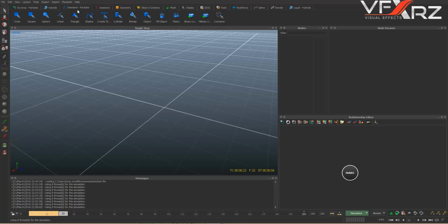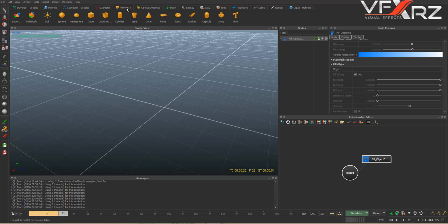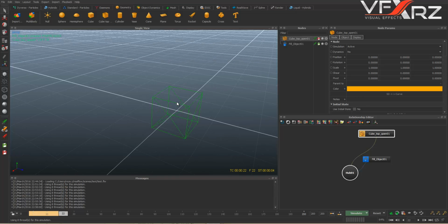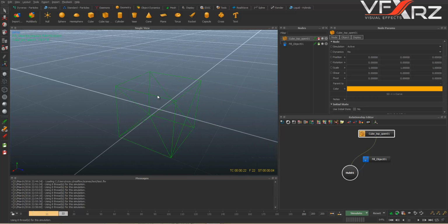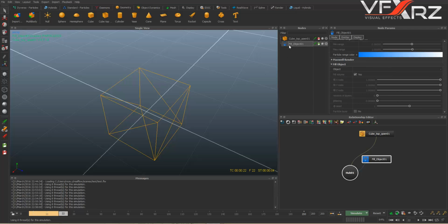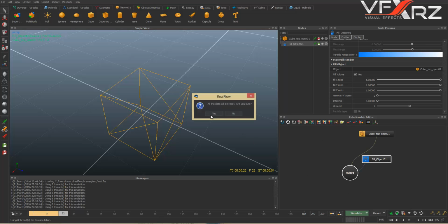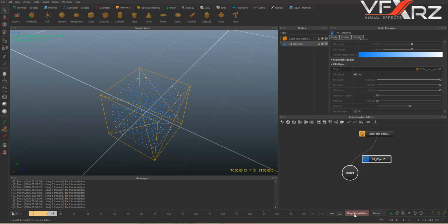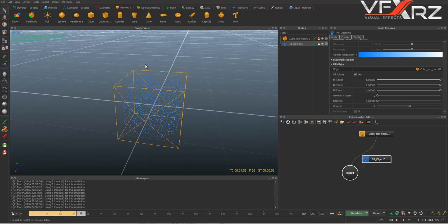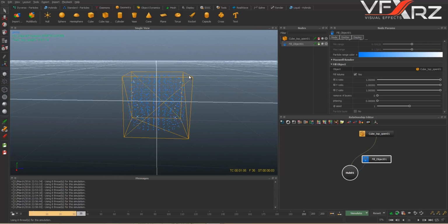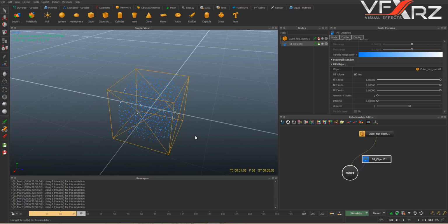this model. Now next is a fill object. If you click fill object, for example, I add this object. When you click this fill object, you should select your object in fill object. For example, I want this object, and then click OK. Now reset, yes, simulate. Okay, as you can see, it fills my object, and my object is full.